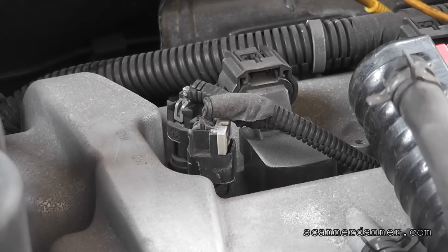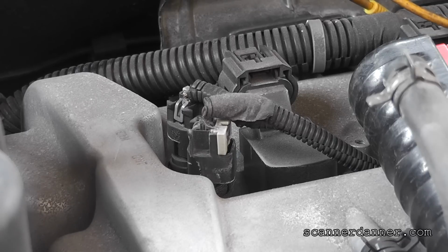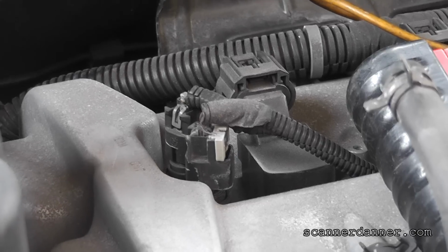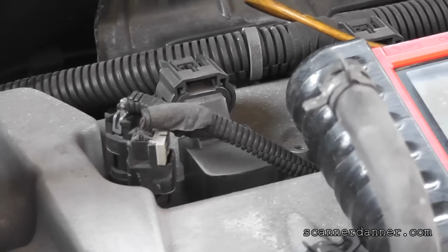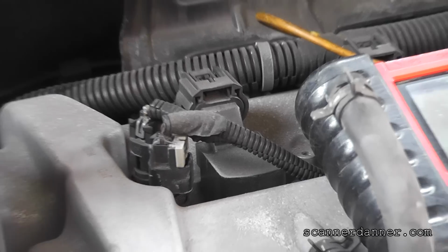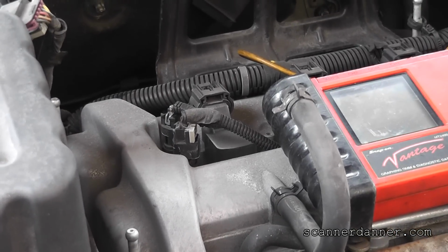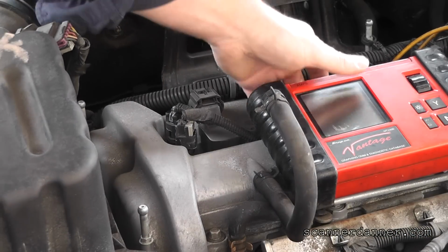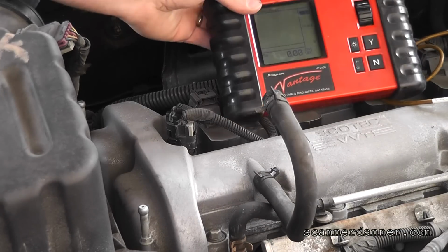It is very common when you have a solenoid failure that when you start back probing and moving connectors, the solenoid will actually come back to life because you've really momentarily fixed a problem internal just by touching it. Very common. Not sure that's going to happen. I actually hope it doesn't happen, because what that'll do is make you guys question my diagnosis here. But we're going to do our measurements first, see if I can get you a shot of the meter and my test at the same time.